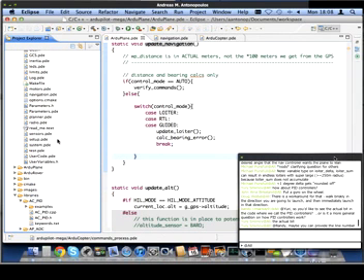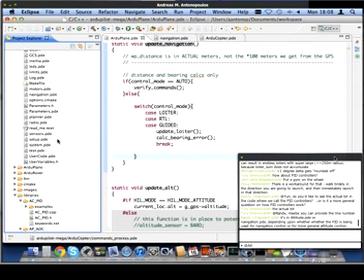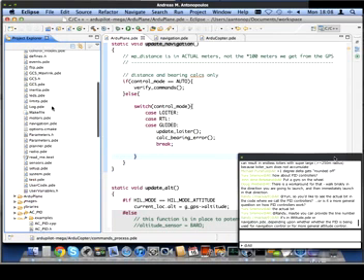Once it gets within either 3 meters of the vertical altitude of the landing point or 2 seconds predicted position of the landing point, it will cut the throttle to 0. That's for planes that have a propeller, which you don't want to hit the ground. You want to make sure the propeller is completely off when you're landing. It is a little bit problematic: we have no throttle cut capability for petrol or nitro engines.